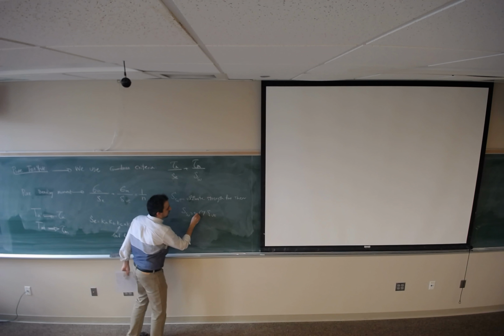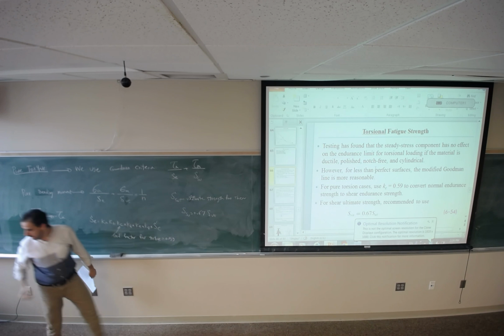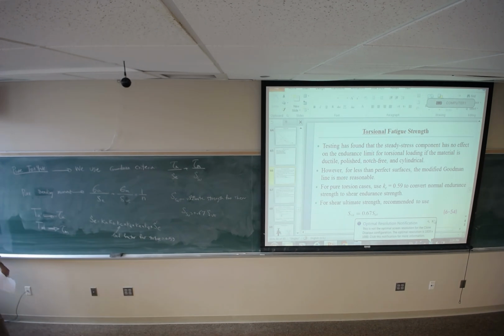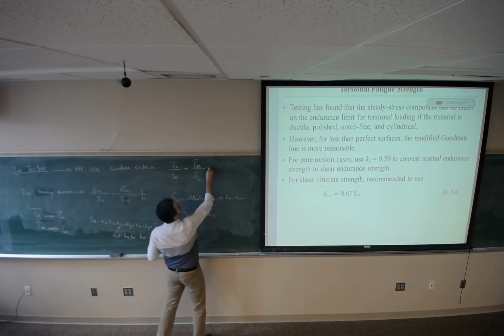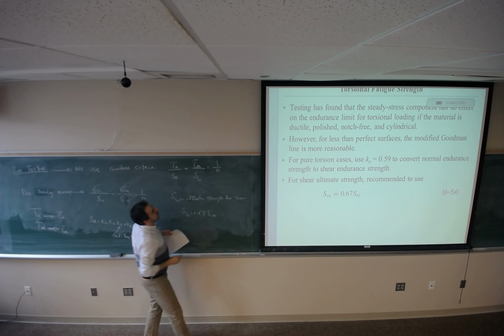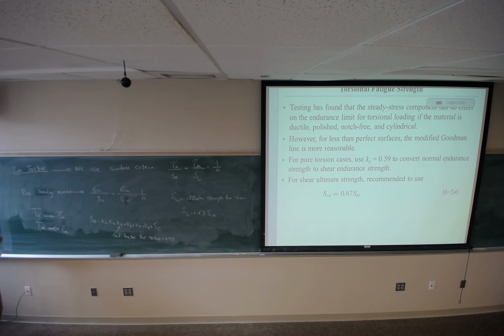These are coming from experimental results. So the recommended value would be 0.65 times S ultimate. Then you are going to apply the Goodman criteria for pure torque.